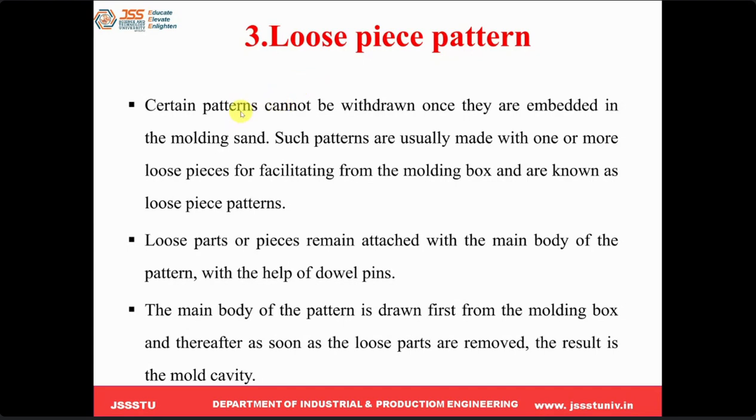Loose piece pattern is made up of different pieces, not a single piece. There are certain patterns that cannot be withdrawn once they are embedded in the molding.